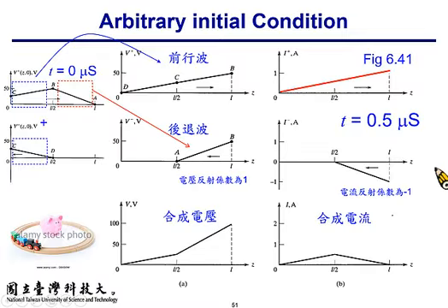And for the V minus signal, you have C and D. With 0.5 microsecond, remember the total length of the transmission line is 1 microsecond. So only half of the signal, say from A to B, reaches the right end and gets reflected. So after 0.5 microsecond, the A to B part becomes part of the V minus signal because it gets reflected from the right end.